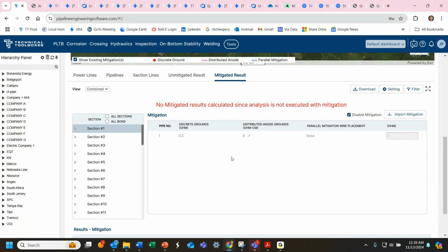Yeah. So, and you could see it arcing. They said they saw it. The diver saw it arcing to a clamp. And the same thing we observed up in, I'll say, the Northeast in a casing. It was a high voltage AC system, 500 kV. And inside the casing was water. When they were taking off the boot of the casing, it was found by a smart pig. The guys could see where the pipe was in very close proximity to the casing. They could see it arcing through the water.